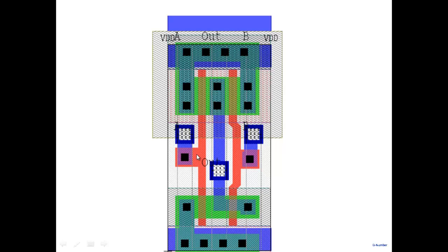So this is simply not possible unless you have a CAD tool which extracts. So the CAD tool will do what you are going to do. It will look for an N plus region. It will look for a poly. And wherever the poly and the N, this green region, intersect, it will say it's an NMOS here. So there's another NMOS here. There's another NMOS here. This is in PMOS. So there's a PMOS here and there's a PMOS here. Poly here and poly here, 2 PMOSes, one here and one here.